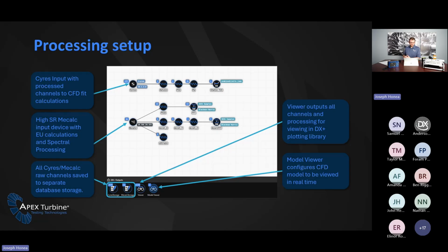And then we are also integrating the MeCalc device, bringing in data which was volts from the device, converting the volts to PSIA for the Kulites, performing an FFT on that data, and then we also had accelerometer data that we were converting into Gs, and then performing an FFT, as well as a strain gauge that we were converting to strain units, microstrain units.